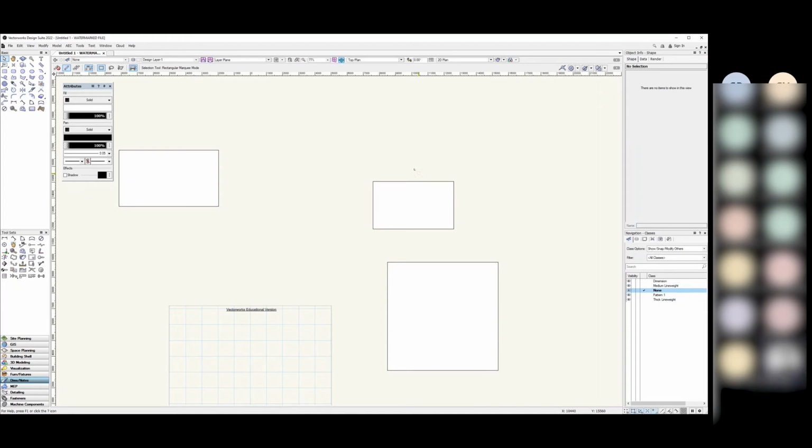So I'm going to give you just 60 more seconds to play around with that. Play around with the ribbon a little bit, get a feel for how these work. Playing with the circle tool in particular is quite an interesting one. By default, it does it on radius mode, where it goes from the center to defining a radius. But you can do it between objects. So for instance, I could do a diameter. Maybe I want to do it from that corner to that corner.